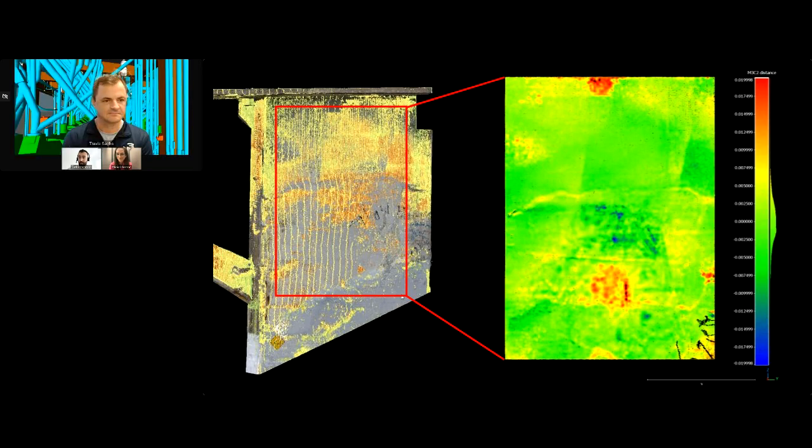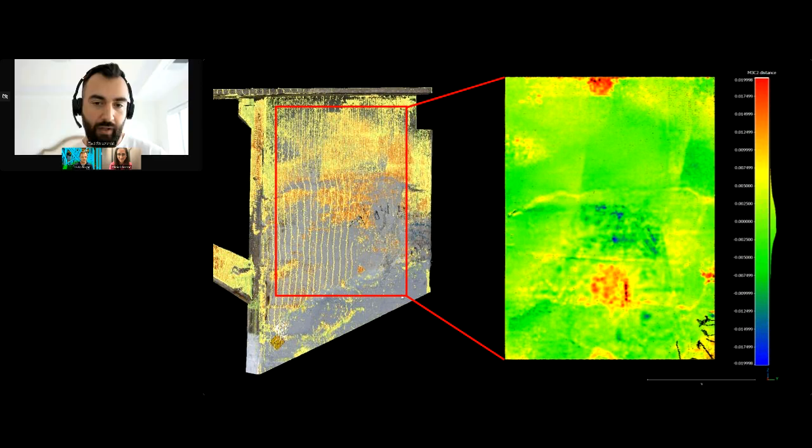And then for a sort of more forensic analysis, I chose one of the really flat elevations, and this is near the abutment of the bridge. And here I'm showing the distance between points again with the laser scan as the reference. And then in that area on the right there, you'll see that there's some green, there's red and blue. So red means that the photogrammetry points were in front, just slightly in front, and then blue means they were behind the laser scan. So these are assigned distances on this cloud-to-cloud comparison.